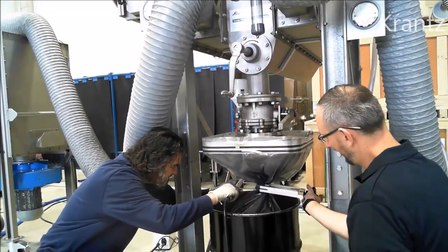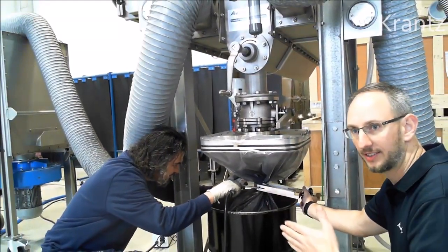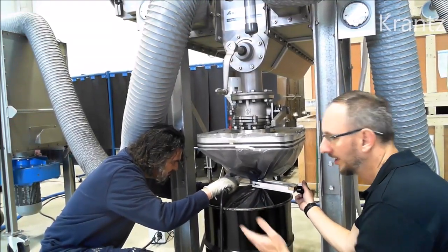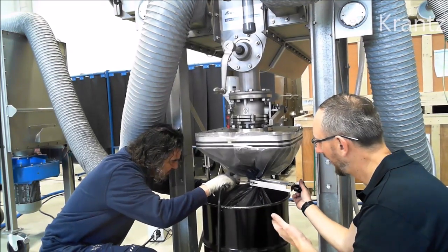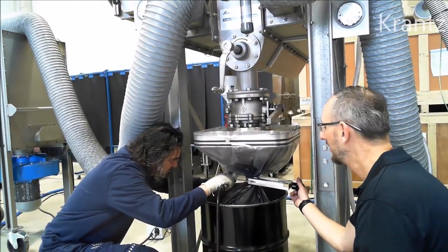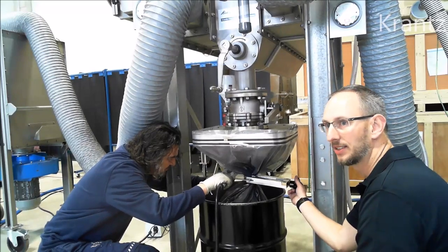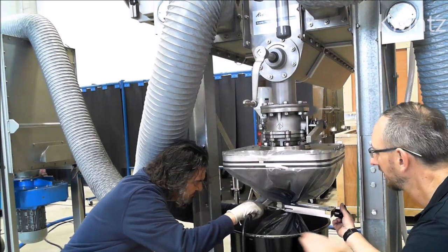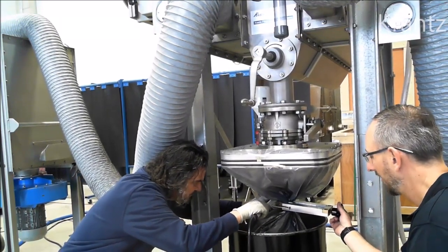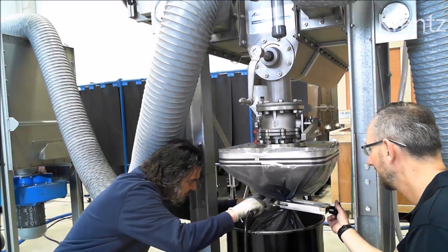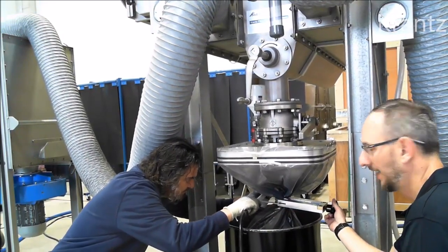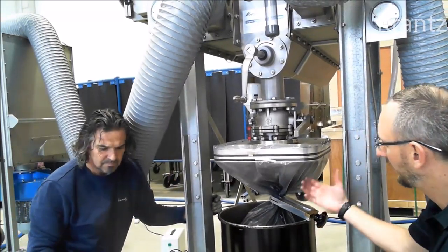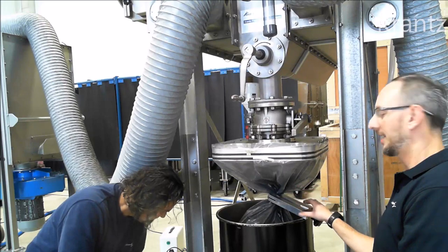Okay. So with the hot knife, as using like a saw, we will cut through the bag without pressure, so it is only by the heat, so that we get a uniform sealing of both ends of the maintenance bag. Once we are through the complete bag, we then go again with the hot knife on both sealing surfaces to ensure that both ends are sealed in the right way. So once this is done, now we have to cool down the bag.